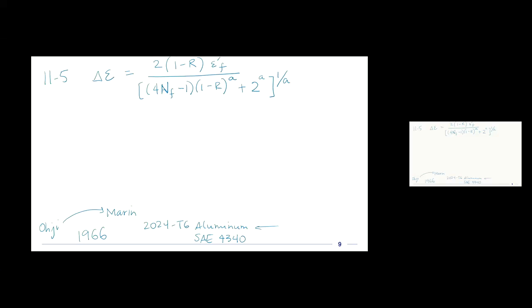So before we had a stress term and we had B and C and epsilon prime F and modulus. And now we have the stress ratio R, which gives an indication of that non-zero mean stress, and A. And we have our strain coefficient here, and we have an exponent A. Okay, so it's fewer variables, but a more complicated expression. R is the stress ratio.